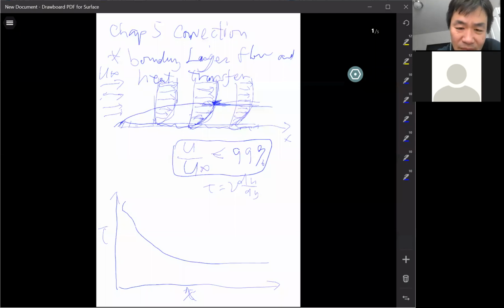Okay. So the shear stress along the plate will look like that. It's actually very big in the beginning, at the tip. Based on this equation, it's very big at the beginning, but it will gradually decrease because the du/dy becomes smaller along the plate in the x direction, because the profile becomes more gradual later in the flow. Later on the plate, the shear decreases like this.